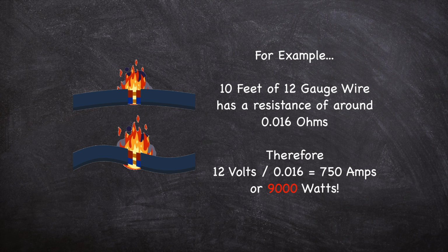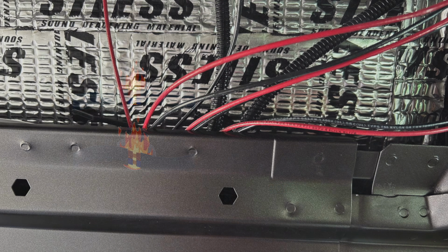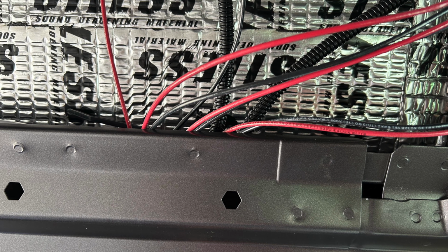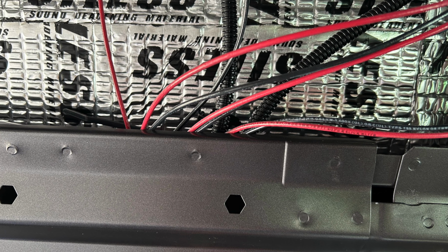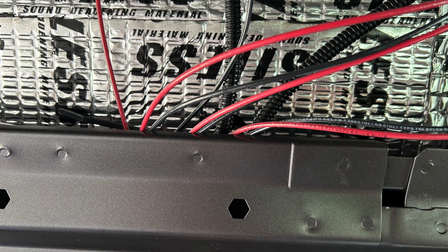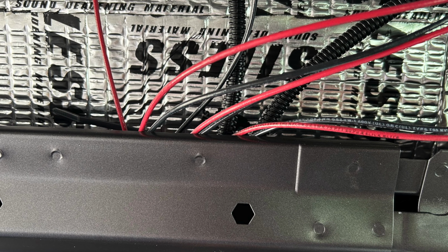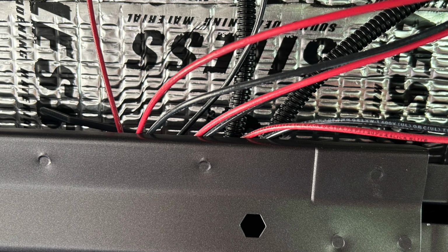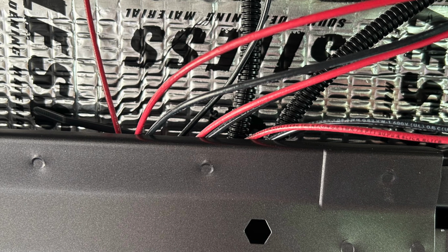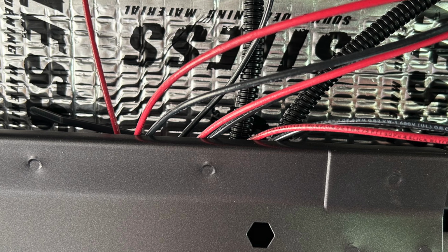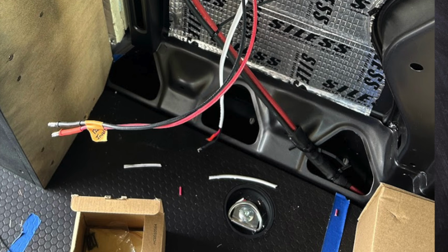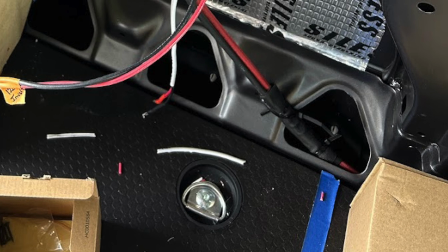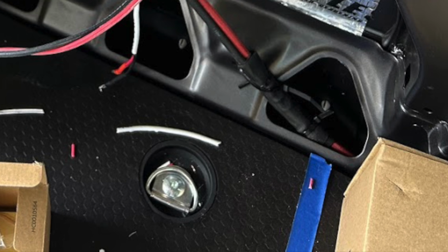First, prevent wires from shorting in the first place. A wire will short circuit when the current carrying metal inside the sheathing touches grounded metal or another ground wire. This can occur, for example, when a positive wire rubs against a sharp edge and wears through its protective covering. Be sure you have added additional protection where this may happen. Use wire loom, rubber, plastic, or other protective materials as needed.